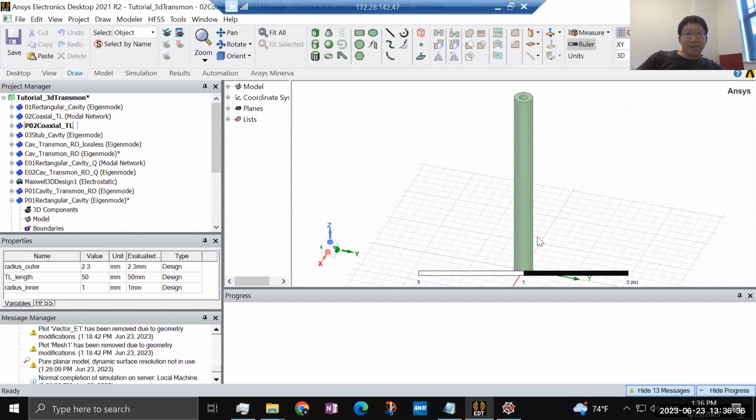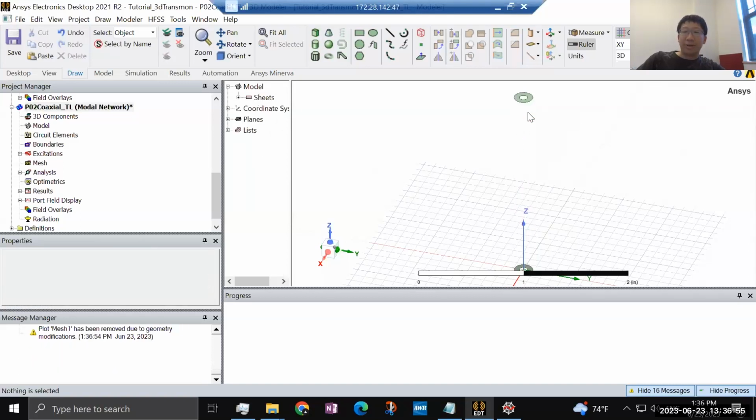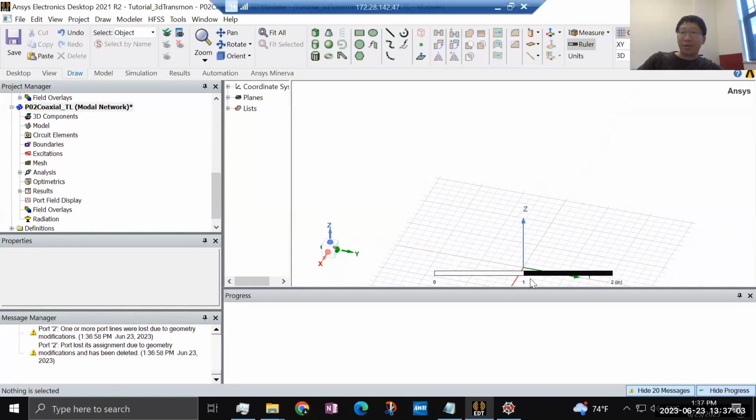By the way, there's an answer to this question from the chat. The Meissner effect cannot be modeled with HFSS. Instead, the London equations have to be solved. Yeah, I think that is true. In HFSS it's generally sufficient to just model that with a perfect E boundary condition. That serves most of the purposes for microwave simulations.